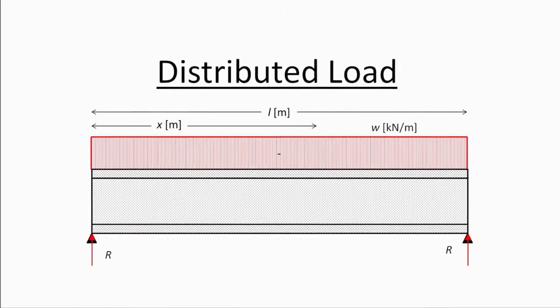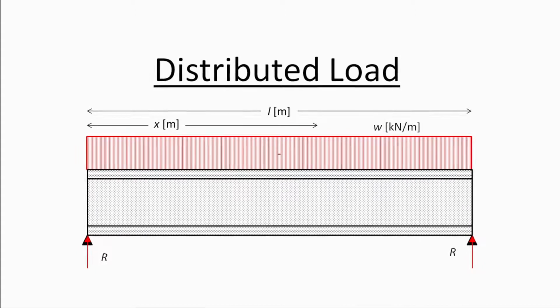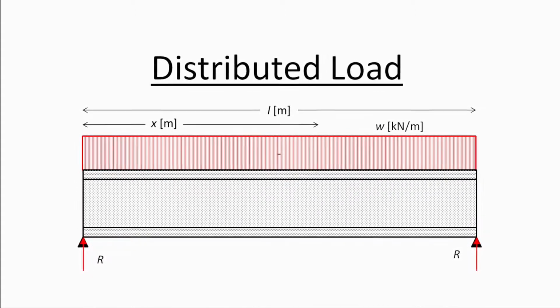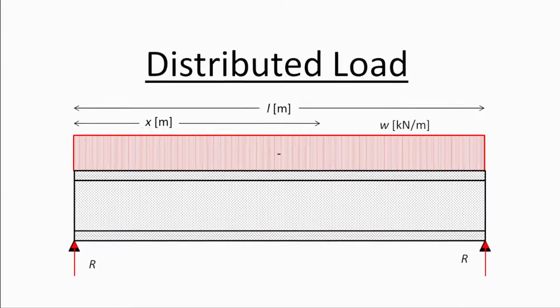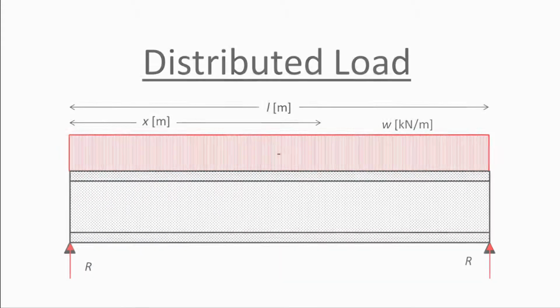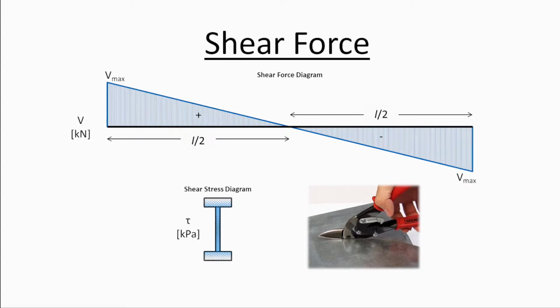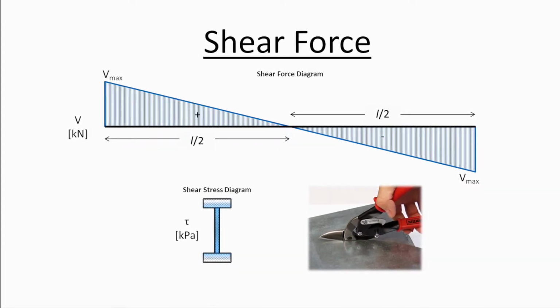The loading of a joist is calculated through its tributary area and types of loads. The loads are given as a pressure. The loading can be expressed as a line load, as seen in the diagram. It is assumed that the joist is a simple beam. A shear diagram can be created for the joist, and a shear stress diagram.